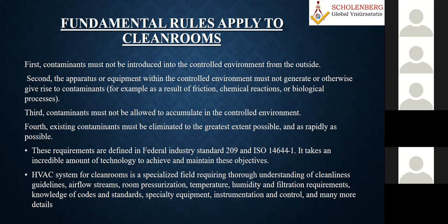I don't know whether I've shared this experience with you. This was probably 1989 or 90 or 91. I was at the Nasik currency note press, and it was a printing press. In a printing press, maintaining humidity is very, very important. Otherwise, paper being a hygroscopic material, you don't get the quality of the notes you print. We had a very tough time.